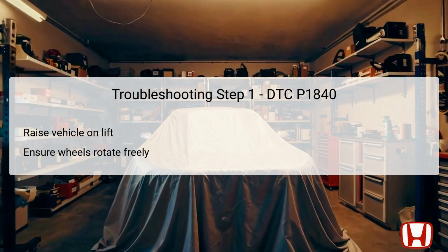The reasoning behind this step is to eliminate any potential obstructions that could interfere with the sensor's readings during the confirmation procedure. It's essential to complete this step thoroughly, as any hindrance to wheel movement could skew results, possibly exacerbating the issue at hand. Grasping the functionality of the wheels in gear engagement is vital for diagnosing the TCM and CVT speed sensor effectively.